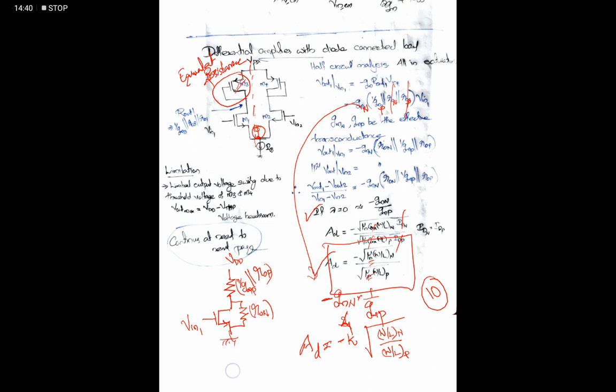Then the gain 10 equals 4 into root of some x value. You can find the x. From that x, you can define the value of (W/L) of n and (W/L) of p. That ratio we need to design. That's all. We don't need to specify the value of W or the value of L.